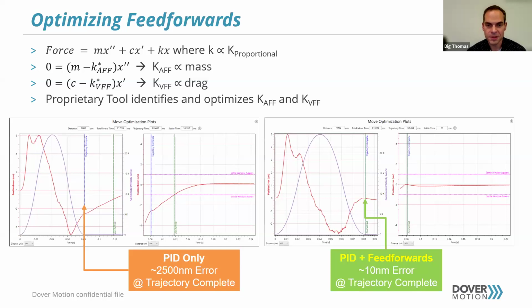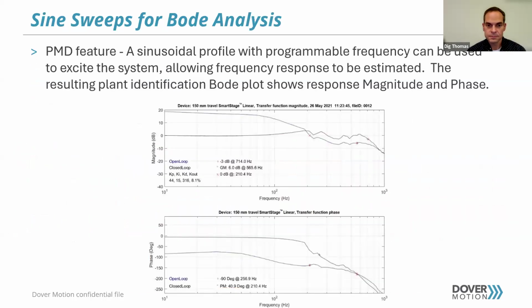So in terms of increasing throughput and reducing vibrations in your system, this has a huge advantage. This profile also uses the S-curve or jerk that we discussed earlier, so again, trying not to excite resonances within the system or the structure. In addition, by adding the feed forwards, you're able to see very good stability right when the trajectory is complete.